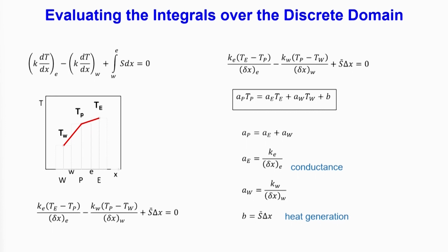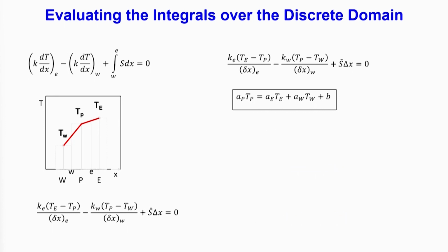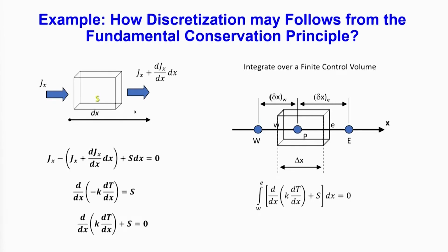So, maybe one slide back. So, you have the control volume and P is its representative node point. So, the source term formulation is taking that the temperature at P, whatever it is, is the same throughout the control volume. That means a piecewise constant temperature.